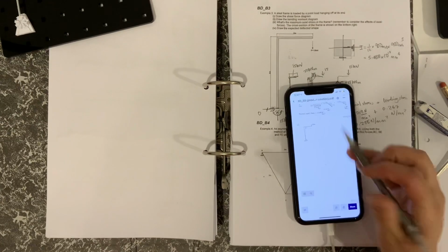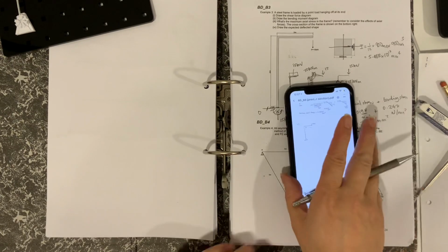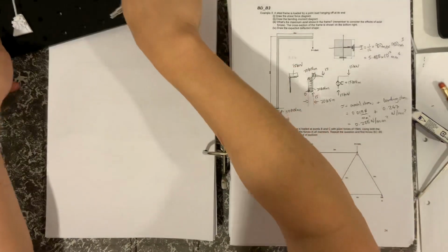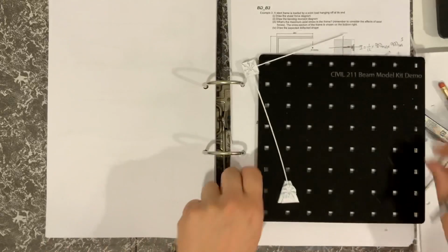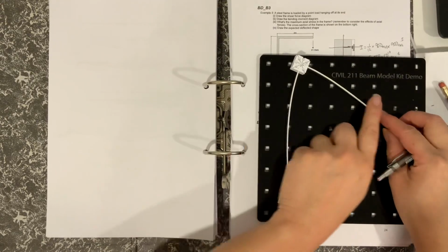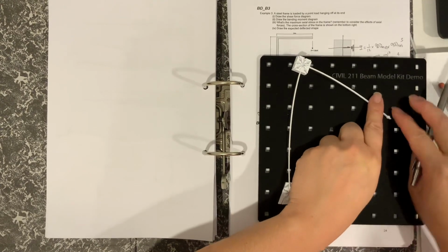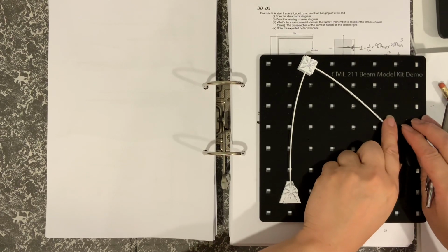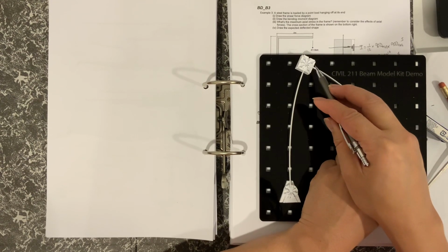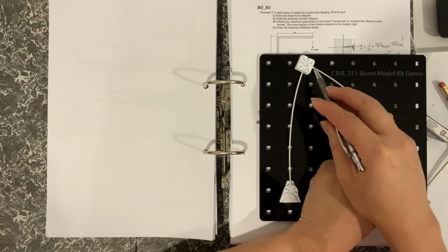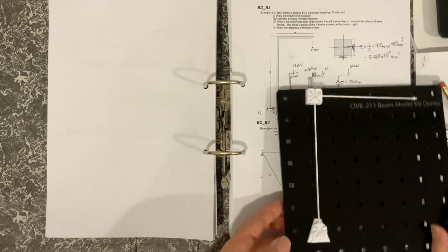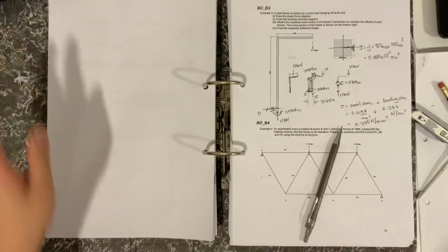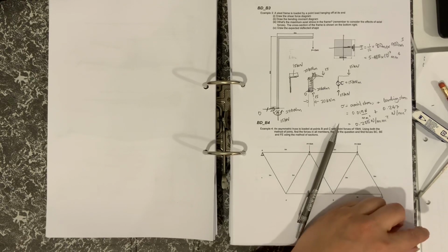One thing to note is that that remains at 90 degrees, of course, because that's the joint. So you can see here when I bend it round, when I apply the 50 kilonewtons at the end there, that angle remains at 90 degrees. So that deals with BD3. Now let's have a look at the next one. I'm not going to do the next one here,